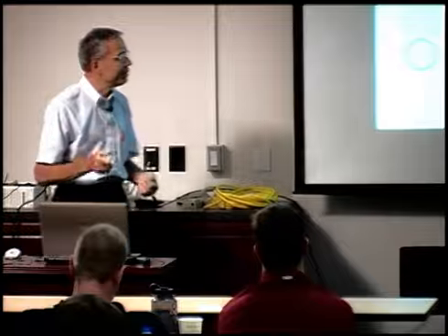Now, if you look at the overall way that we've approached it, and play professor with it a little, as I used to do, what we've done is we've said, okay, you get your loads, factor them up, and that tells you how many piles you have. And then you figure out how long they have to be, and deal with the driving.